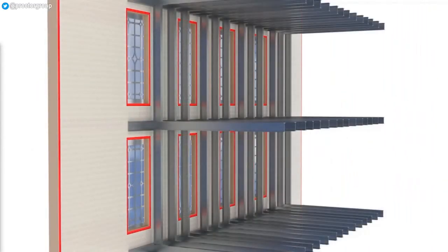Wraptherm is installed on the reverse of the retained facade stonework in a similar way to many self-adhering damp-proofing membranes. However, as Wraptherm is vapour-permeable, it does not adversely affect the movement of moisture through the facade stonework. This helps limit damage that can occur when moisture flow through older stonework is altered by upgrade works.